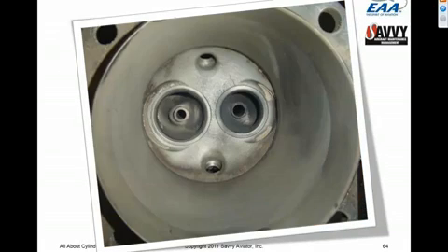Here's one where there are 2 cracks, one that's developing from the exhaust valve boss up towards the top spark plug hole, and another crack that's initiated from the top spark plug hole. It's growing down towards that exhaust valve. Eventually, those two cracks probably would have merged. But again, this is the sort of thing that we can see with a borescope if we look nice and carefully at it.